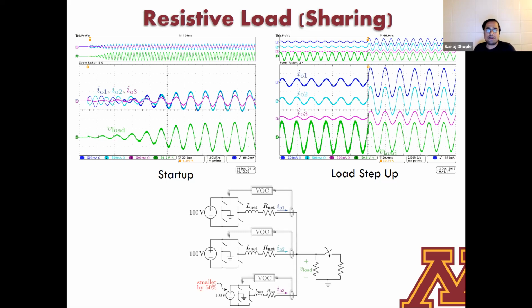And then the figure on the top right is showing you what happens as a result of a load step. So you see that there is a load step that's instituted, and in the middle of that particular waveform, all the currents increase in amplitude, and they still maintain power sharing even after going through this large signal transient with no communication. The load voltage remains rock solid, and we still maintain synchronized current waveforms getting out into the load.